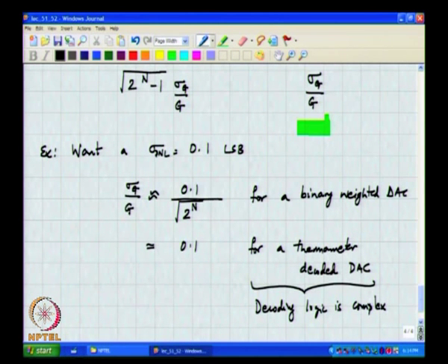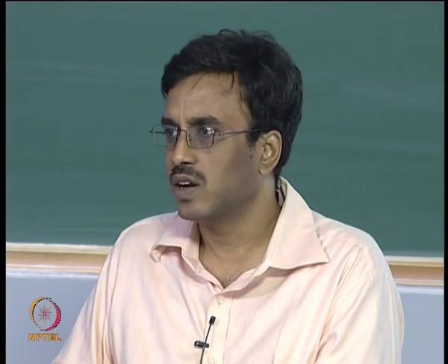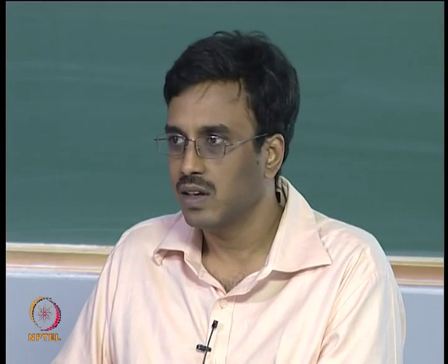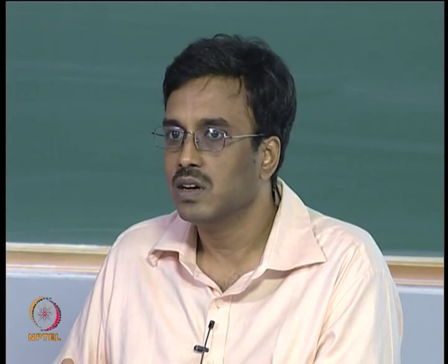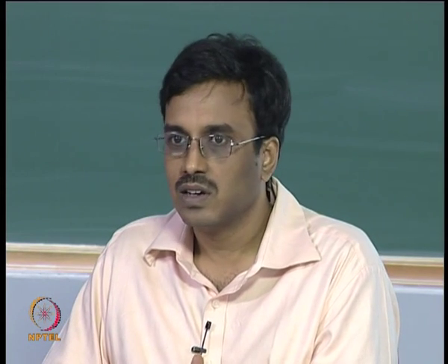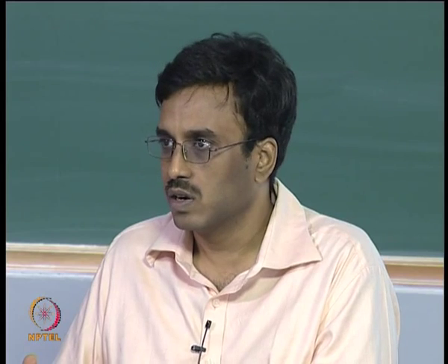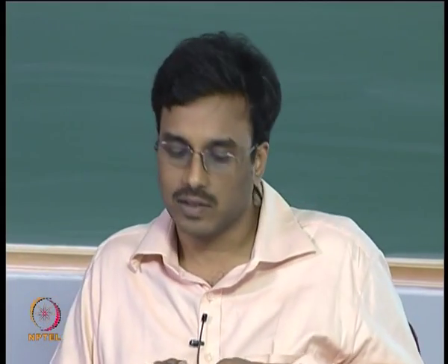Okay. So, in the next class we will continue with more discussion on these ways, and you know that these are two extremes, all right. So, in practice when you have a high resolution DAC, the best path is probably the middle path, which is neither all binary nor all thermometer, right, something in the middle. Okay. So, we will continue after a break. Thanks.